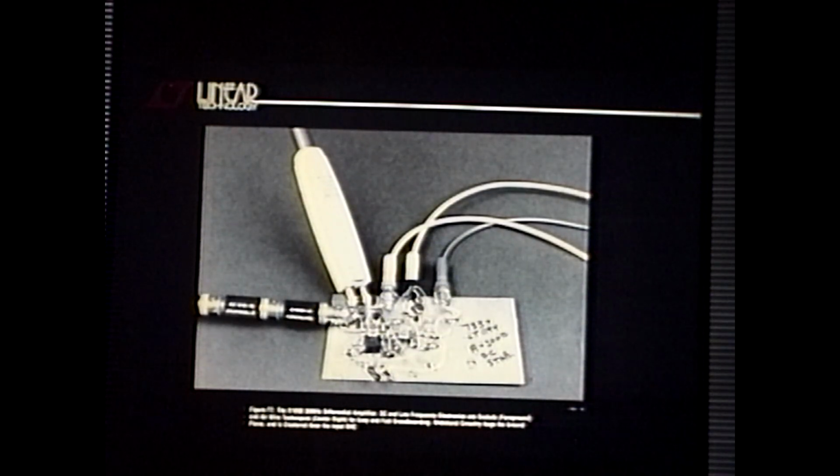But if I'm wise, I'll verify the integrity of what I put into this amplifier with a true differential FET probe. Why do I use a differential probe? Because in millivolts of input, I don't trust my ground integrity. I want to look differentially. So if Tektronix did their job and the output of the pulse generator looks good, my millivolt level pulse down here should look good. But I want to know it. I want to see it. So I verified, and I verified differentially because I think the ground integrity is good, but I don't know for sure.